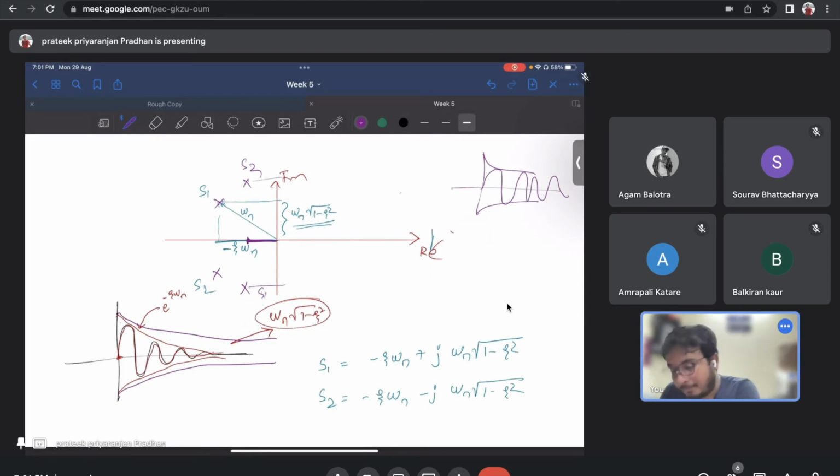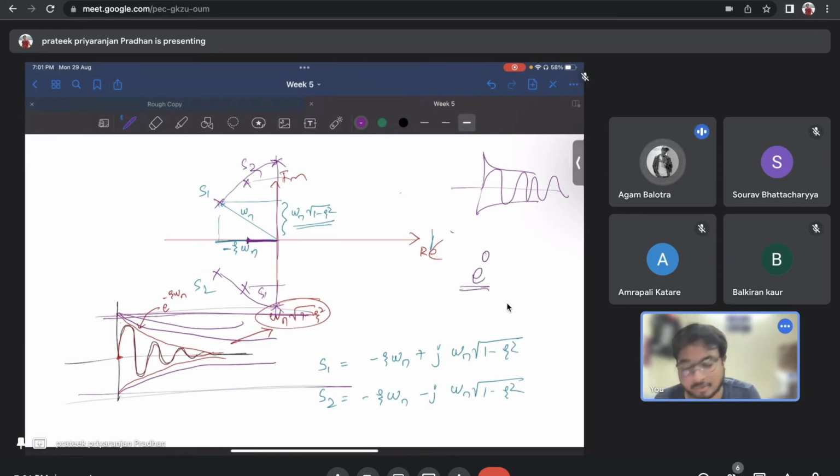So when the poles come to the imaginary axis, then there is no dying out, no negative real part. The system is pure frequency. Then there will be a constant for e to the power 0, the real part is 0. So that frequency, at which there is no damping, no dying out, is called the natural frequency of the system. We have not touched the system yet. Whatever it naturally had, it has now.